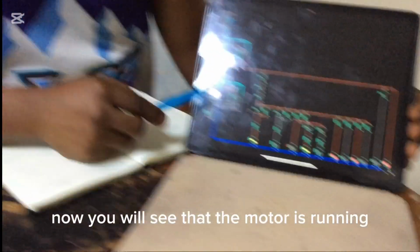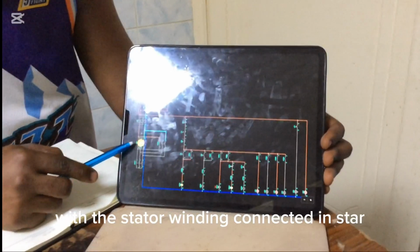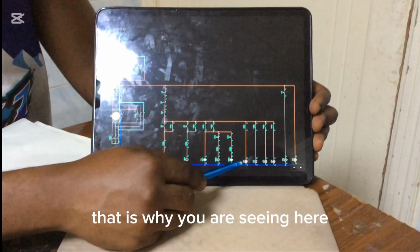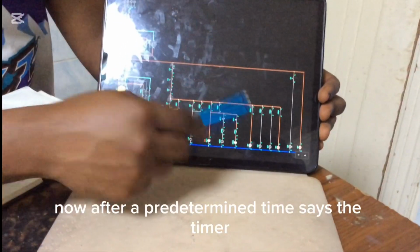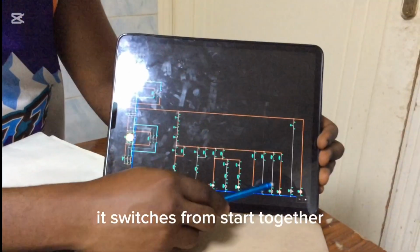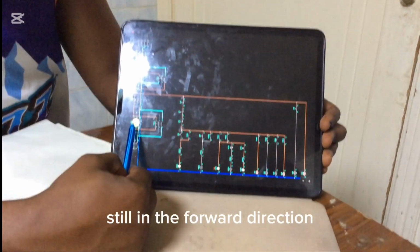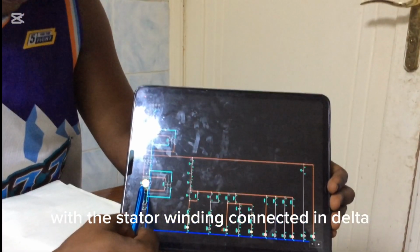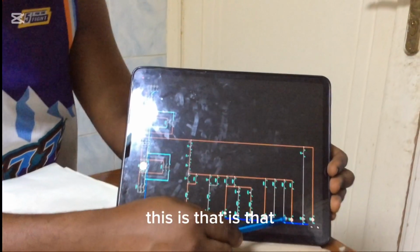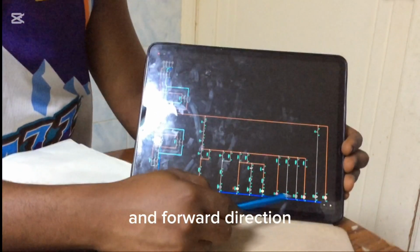Now you will see that the motor is running in the forward direction with the stator winding connected in star. That is why you are seeing this here. After a predetermined time set by the timer, it switches from star to delta. Now you can see the motor is still running in the forward direction with the stator winding connected in delta. This indicates that the stator winding is in delta and forward direction.